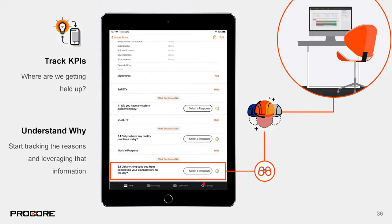So along with the daily log every day, we asked each of our supers to answer 3 questions. We created an inspection form in Procore and asked these questions. Did you have any safety incidents today? Do you have any quality problems today? Did anything keep you from completing your planned work for the day? If they answered no to all 3, great. We had a great day in the field.